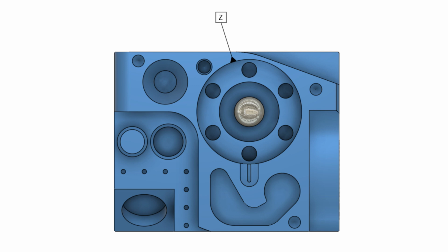We can then use this to fix the template of the circular planes. This means the circular planes will always be linked to the datum bore. So if the datum bore moves, then the circular planes will always move with it. So let's see this in action at the CMM.